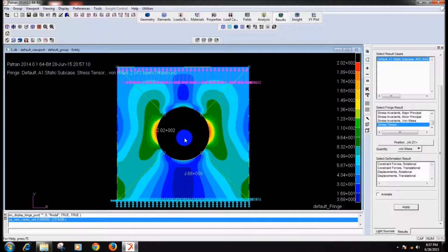But it really depends on the stress concentration, so we have to follow the book of Peterson and find out the stress concentrations that would be applicable in this case. So typical problems of plate with a hole will end up with a stress concentration Kt of the order of 2.6 to 3. So we should also get that.